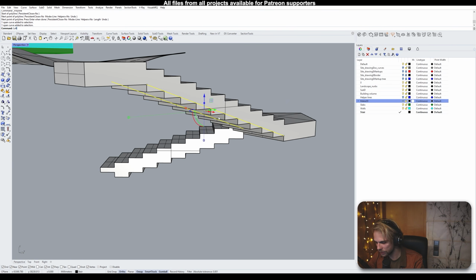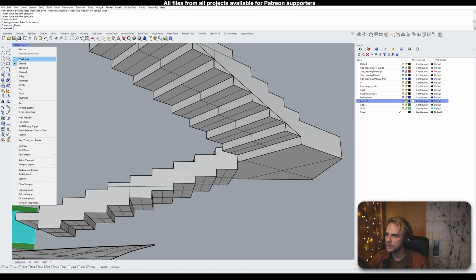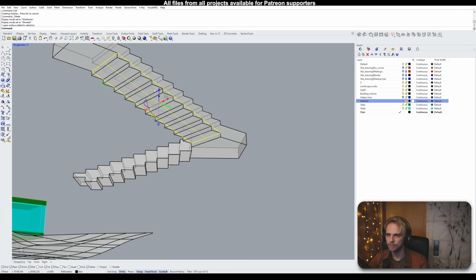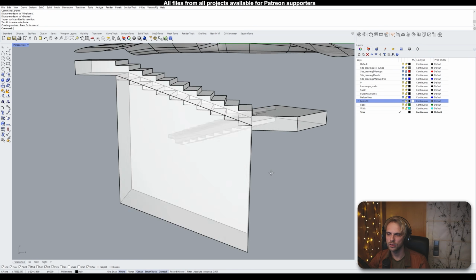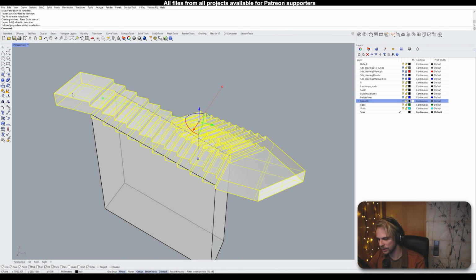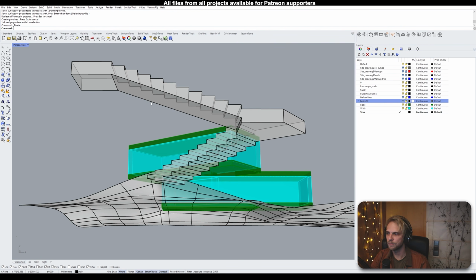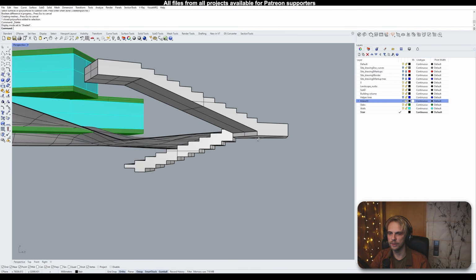We create a loft between them. Just a surface. It's hard to see the surface. Let's go to shaded view. Sorry, wireframe view. That didn't help. Ghosted view perhaps. Anyway, there's a surface here, right? I will just extrude it to make it into a really big boy. And now with it, we can select the staircase and Boolean difference out the back plate with the loft, basically.